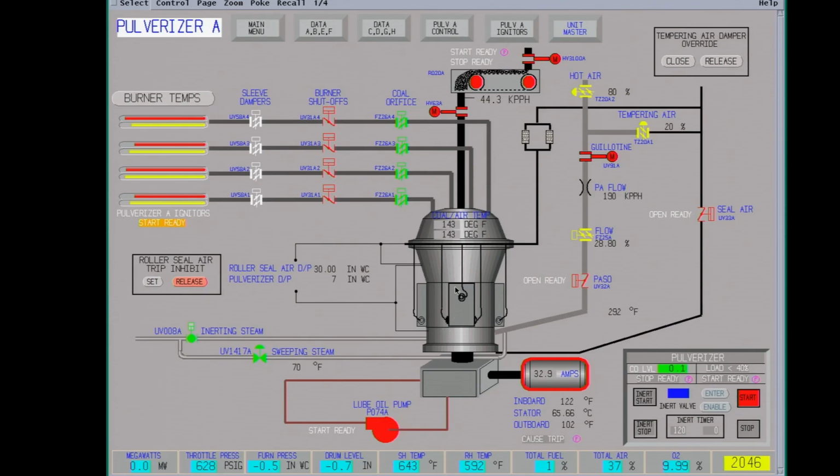The older style pulverizer had a ring pushing weight down on the wheels, and the wheels were like a planetary tied together, and they rolled in here independently, and they were prone to skidding. This one, the rollers are stationary and the table turns, so it doesn't skid quite as much. They will plug up, and there's some other issues they'll have.